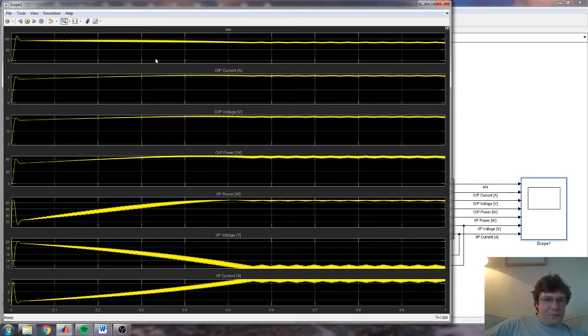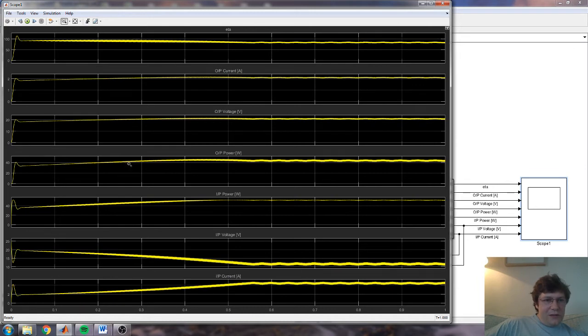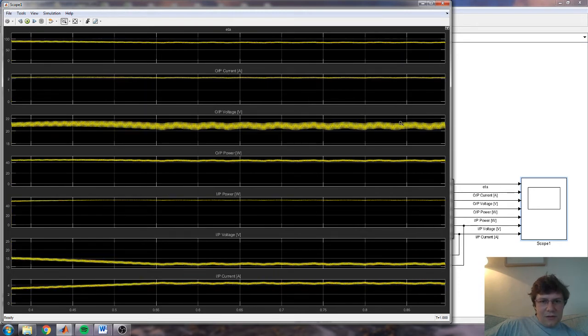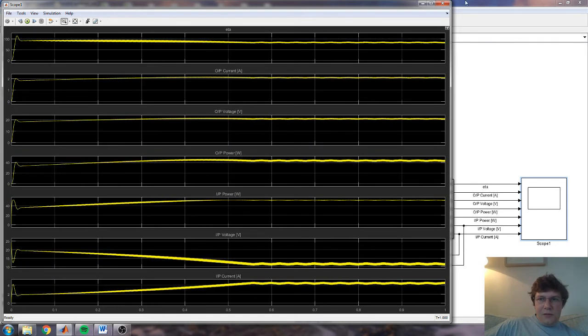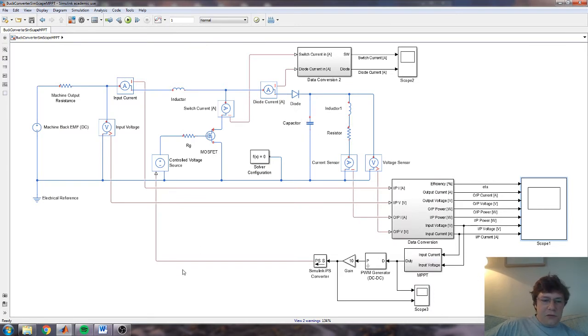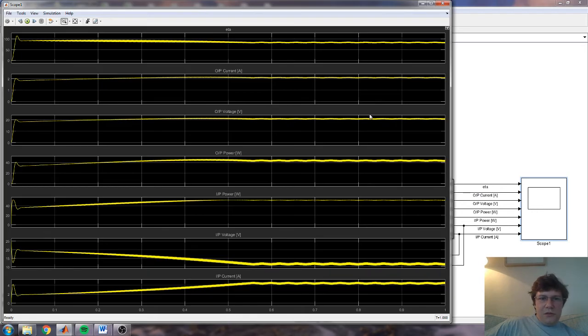So, what's happening? Well, the output voltage is rising to a maximum, more or less. There's a little bit of ripple, and I suspect the tops of the ripple are probably just about equaling the top of that bit there. We might even be able to zoom in on that. Yeah, roughly speaking, that's about the tops of all those and the top of that bit there, just about. There's some ripple, and if you wished, you could have less ripple, and the way you do that is make that cap a bit bigger or increase your switching frequency. But as I said, I don't really want to deal with a boost converter. You can find the equations for their design online.